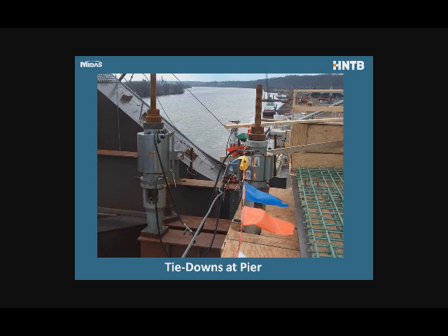You can see the knuckle joint in the background, and then the two jacks in the foreground, and the cross beam. They're pushing down on that end floor beam and prevent that arch from toppling over. It did lift up a fraction of an inch, so you could actually see air underneath the bearings. And there's a backup system, so in case the main set of tie-downs fails, there's a secondary system just for redundancy.